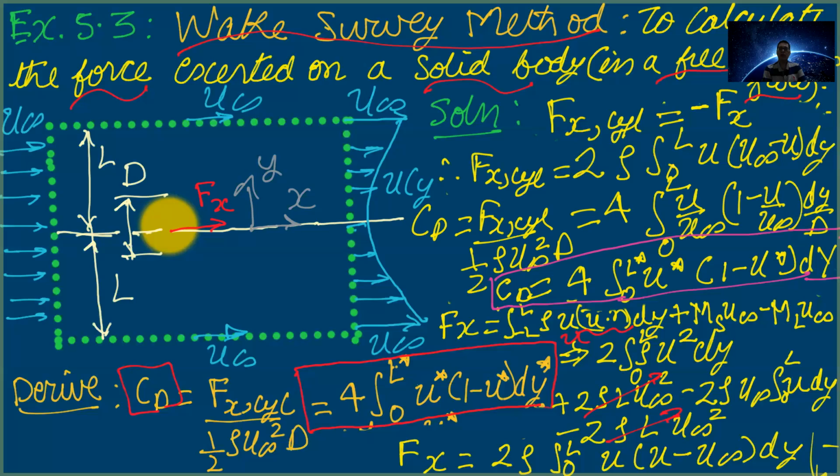It may so happen that you are given velocity at certain boundaries of the control volume. Intentionally, they are not given at other boundaries, because by mass conservation you are supposed to obtain the mass flow rate, such as we obtained from the side walls in this problem. Okay, don't miss this. This is one of the trickiest problems in this topic.